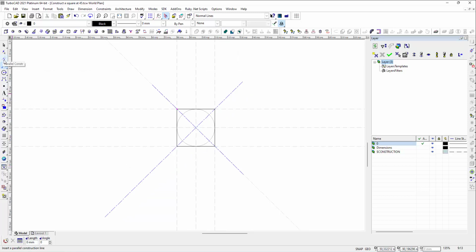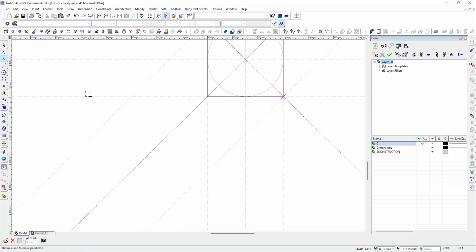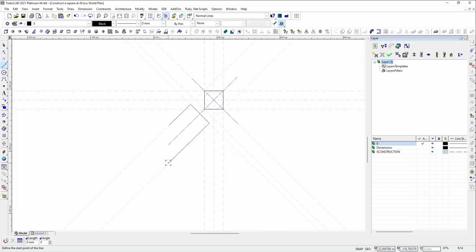All that we do is go parallel to the main center line, draw a light construction line out parallel to the center line or the main axis, and then we can also say to ourselves what is the closest distance that we want to start off with. So I'm going to draw 10 millimeters away from there, so I'm going to say -10. So now I know there's a 10 millimeter gap between the branching pipe and the auxiliary view, and then I can draw that as far as I need it up to the distance that meets with the main pipe.